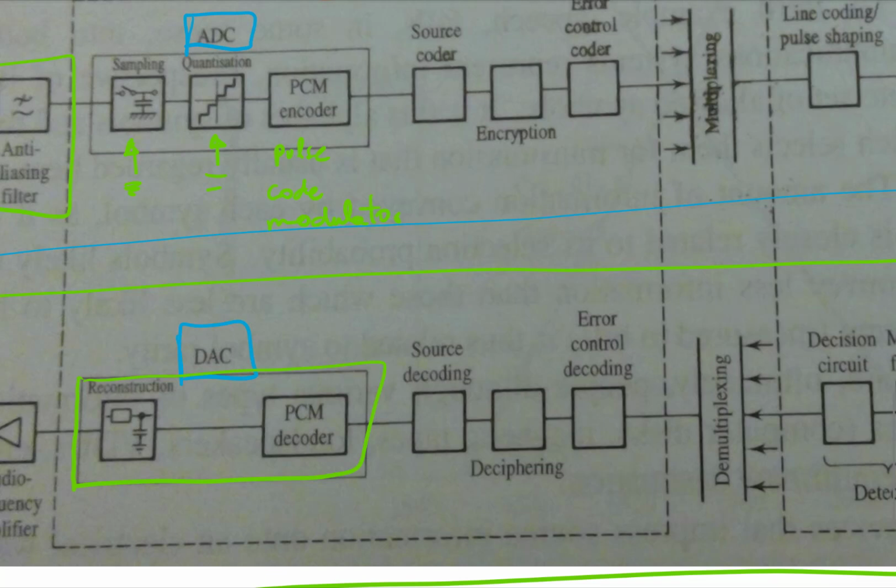The digitization of analog signals usually increases the signal's transmission bandwidth, but it permits reception at a lower signal-to-noise ratio than would otherwise be the case. This is an example of how one resource, bandwidth, can be traded off against another resource, transmitter power. So the codecs make widespread use of sophisticated digital signal processing techniques to encode efficiently the signal prior to transmission, and also to decode the received signals when they are corrupted by noise, distortion, or interference.